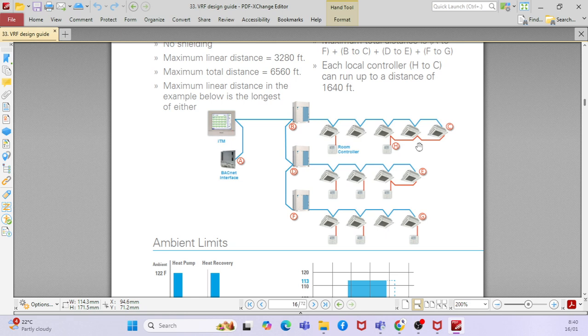For example, you have a building in one location and another location. How are you going to run the chilled water pipe, or run the VRF system, or go with separate DX, which is easier operation-wise? Space availability, maintenance, everything, you will see that, then you will decide. No one will say that you have to go with the VRF system, the air cooled chiller, or the water cooled chiller. Based on the project, you can decide which system to go with, based on the different points which I shared with you last time.